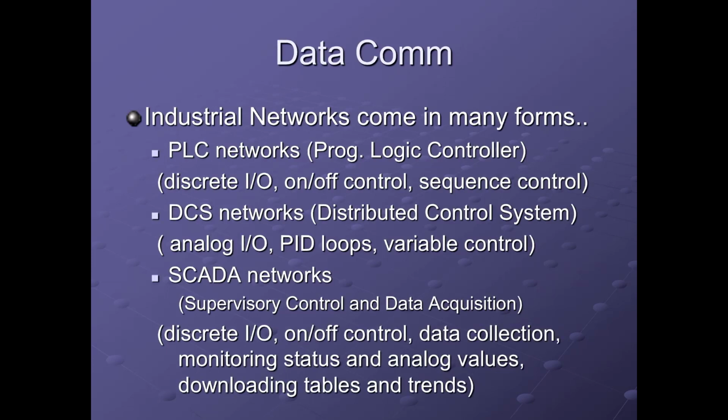The first one is a PLC network. Knowing that some of you have worked in the field and have taken, if not one PLC course previous to this course, maybe more, you know about PLCs. When you have a logic controller that wants to communicate with another logic controller, you would have to network those devices. You'd have to have a network interface module of some sort, or a media access module, to allow you to communicate between those two controllers, and this would be called a PLC network.